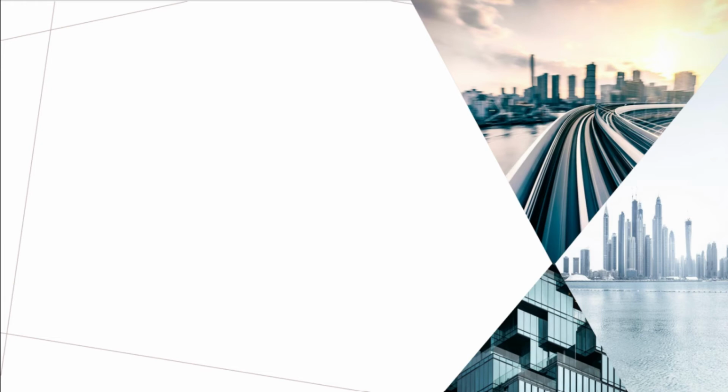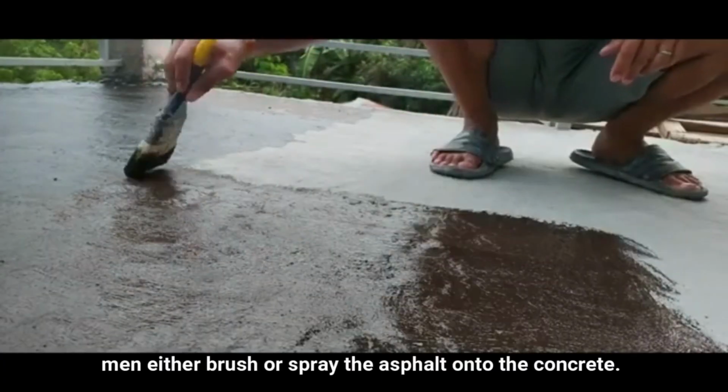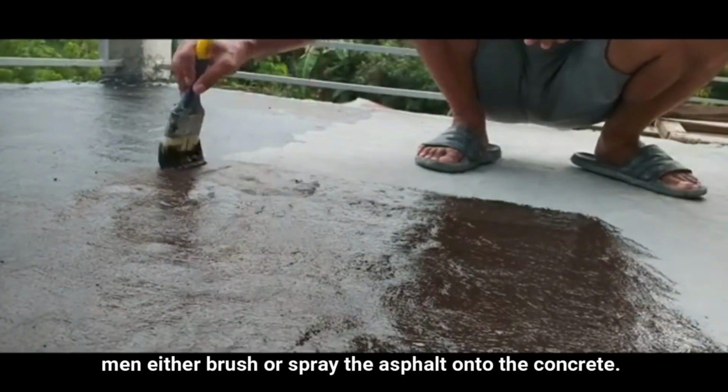If the surface will touch earth, it may need to be protected from moisture. Concrete is waterproof if a perfect job of placing and finishing is done. Usually, there are small defects which allow moisture to gradually seep through the concrete. Therefore, workmen waterproof the concrete by putting a layer of asphalt on the surface. Then men either brush or spray the asphalt onto the concrete.